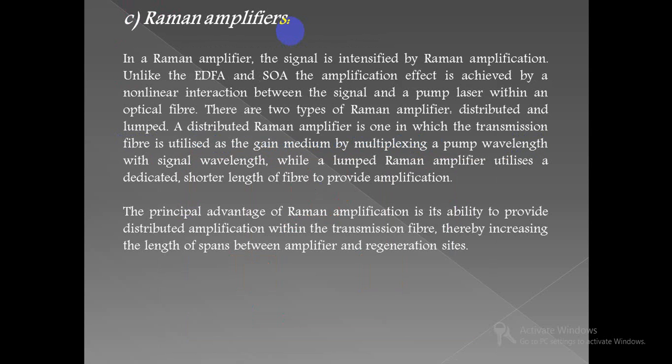Now coming to the Raman amplifier. In a Raman amplifier, the signal is intensified by Raman amplification. Unlike the EDFA and SOA, the amplification effect is achieved by nonlinear interaction between the signal and the pump laser within an optical fiber. There are two types of Raman amplifier, distributed and lumped. The principal advantage of Raman amplification is its ability to provide distributed amplification within the transmission fiber, thereby increasing the length of spans between amplifier and regeneration sites.